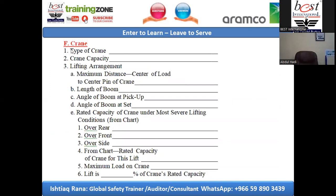Portion F of the lift plan is all about the crane: what is the type of the crane, the capacity the crane is designed for, especially after third party inspection, what they have recommended, the crane capacity and lifting arrangements, the maximum distance from the center of the load to the center pin of the crane, and also the length of boom, angle of boom at pickup, and angle of boom at set, rated capacity of crane under the most severe lifting conditions from the chart, over rear, over front or over side, rated capacity of crane for this lift, maximum load on the crane, and also the lift is what percentage of the crane's rated capacity.